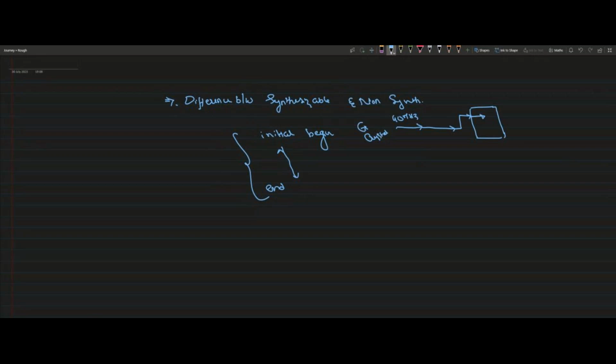I have a 40 megahertz clock. Can I use that 40 megahertz clock directly? No, sir. Yes. How are we going to handle that? We may put a clock generator. Even if you want 40 megahertz itself, it's always recommended to use PLLs. We have MMCMs, the mixed-mode clock manager, and through that you can generate 40 megahertz itself. Let me consider that you have generated a 40 megahertz clock.